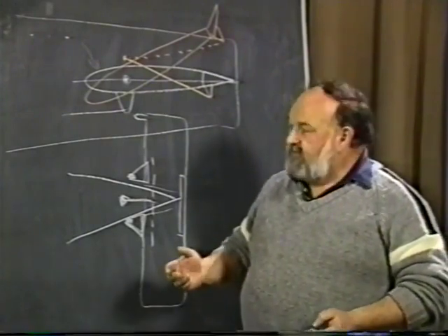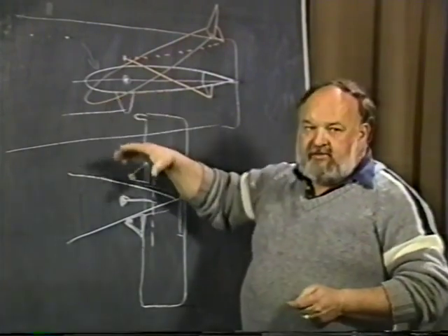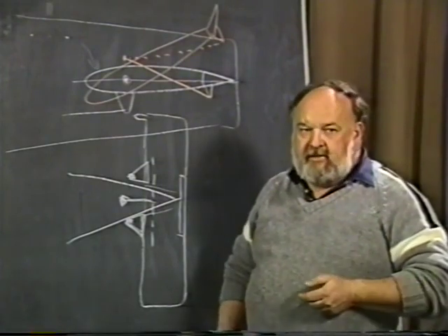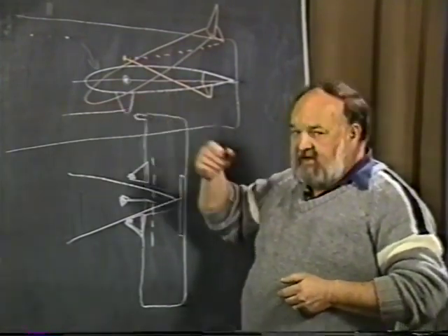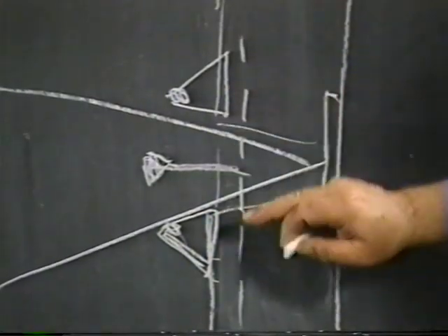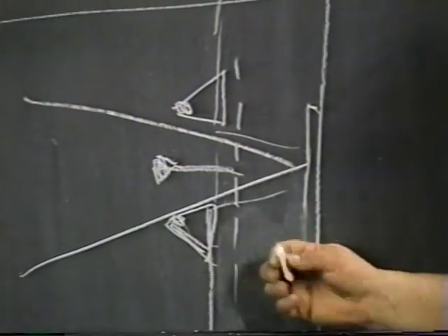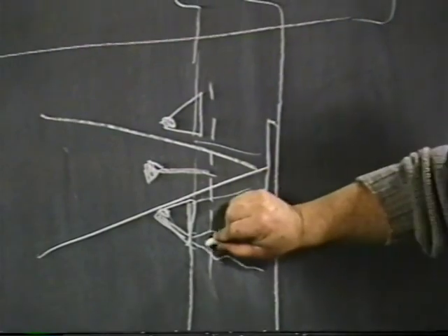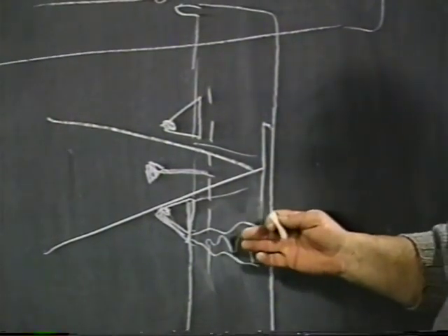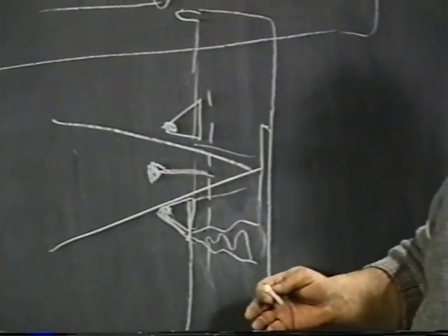What they did to solve the problem is they put slats, fixed slats on the leading edge in here so that they could increase the angle of attack that the tail could tolerate, in this case upside down, but the principles are the same, and that prevented the tail from stalling at these extreme angles of attack. The delta wing surfaces for us, putting it out in here, gave us the advantage that it caused a vortex to roll over the surface, which caused a nice vortex to build up on the tail back in here, and it kept the flow attached to this part of the surface. So the horizontal tail could never stall completely at any one time when you got to this extreme angle of attack.